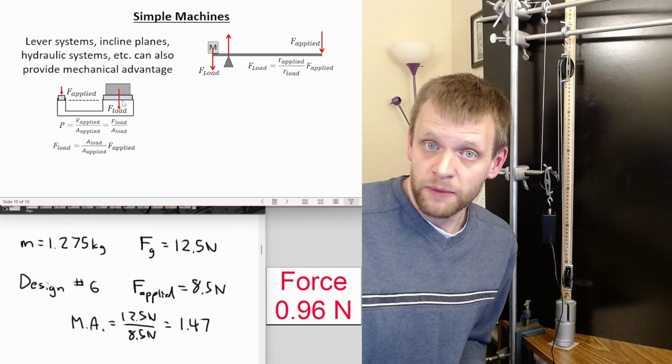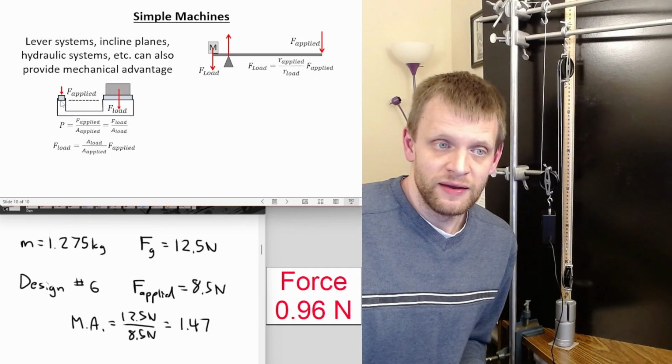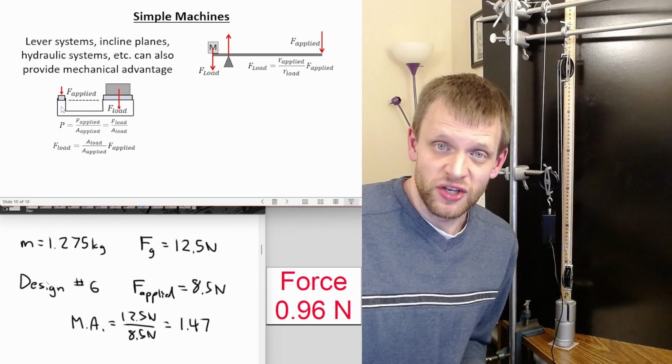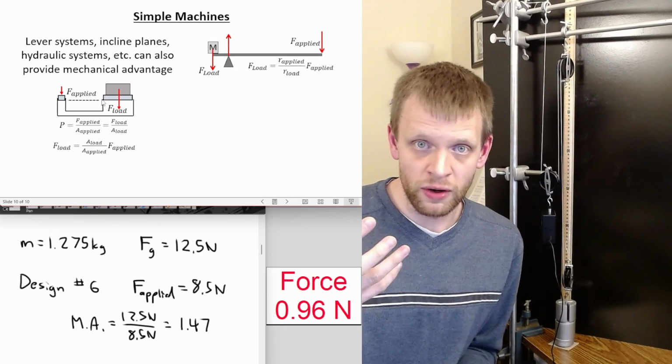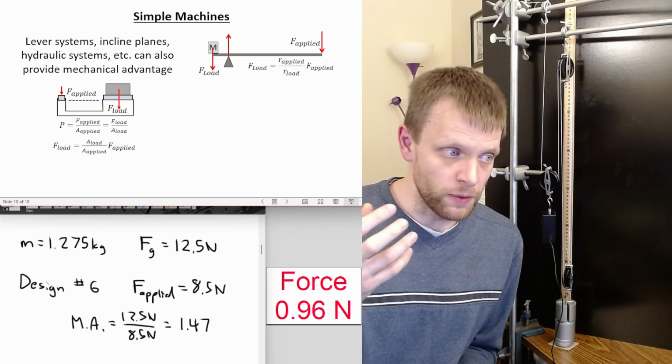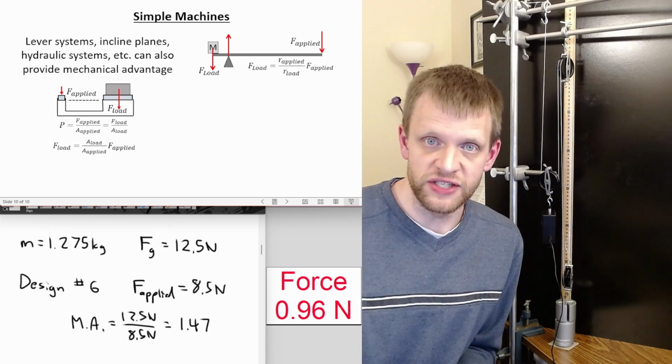But if I want to move this system up or down, me moving a certain distance on this side is not going to displace very much fluid. It's not going to move this side up very far. So I can get more output force, but I have to apply that force over a larger distance.